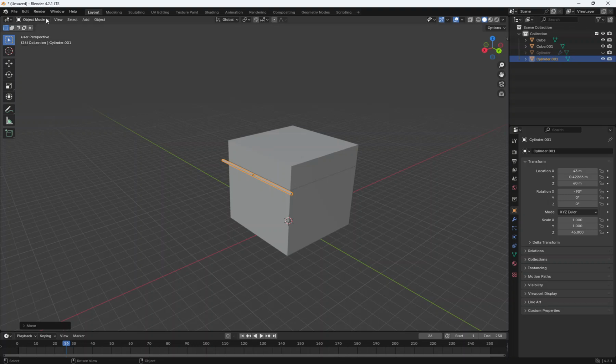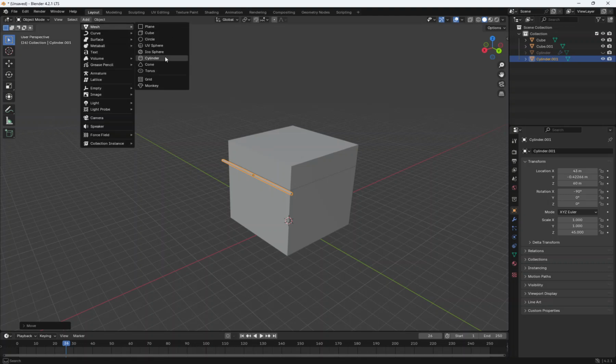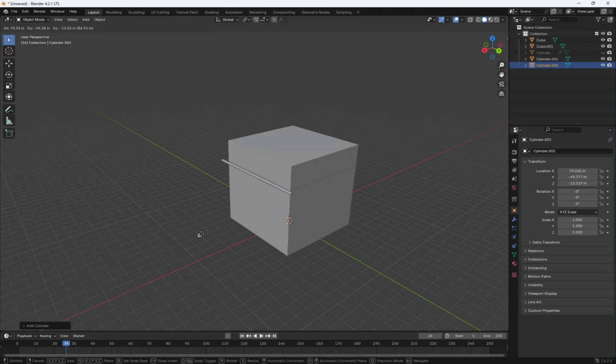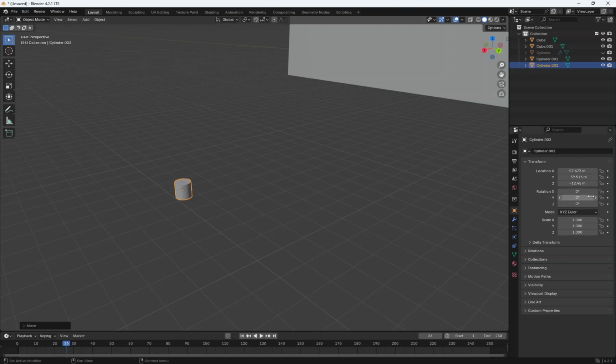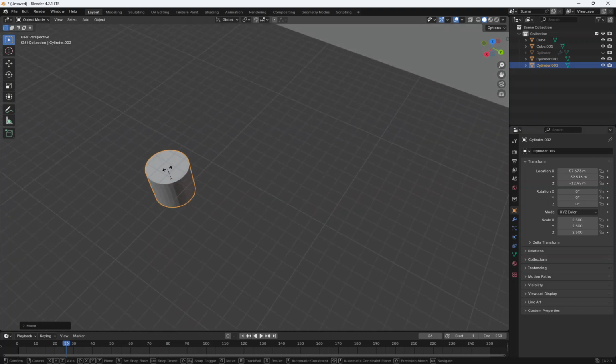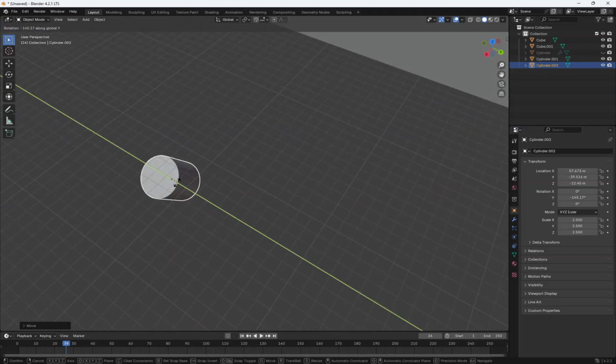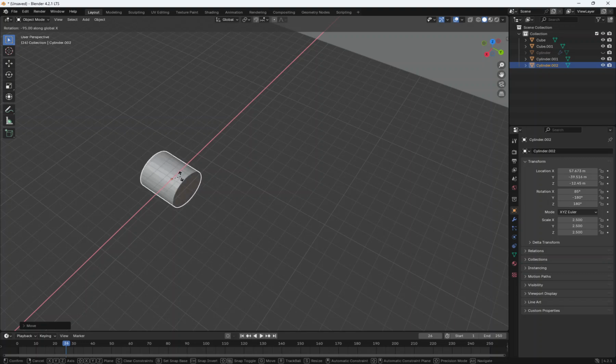So what we're going to do for that is create another cylinder, mesh cylinder. We'll move that out here. And in this case, I want the diameter to be 5 millimeters. That's what I made it in Onshape. So again, these are going to get doubled, so 2.5 in all of them for now is fine. And we want to rotate it about the X-axis in this case. So I'm holding down Control, and I'm going to get it to -90.